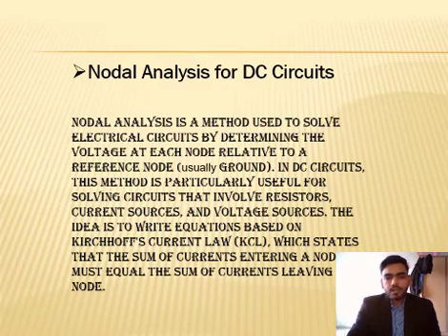Node analysis for DC circuit. Node analysis is a method used to solve electrical circuits by determining the voltage at each node relative to a reference node. In DC circuits, this method is particularly useful for solving circuits with current sources and voltage sources. It uses equations based on Kirchhoff's current law, which states that the sum of currents entering a node must equal the sum of currents leaving the node.